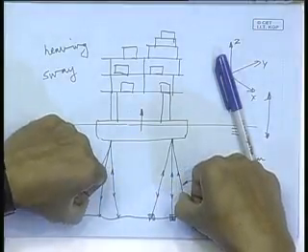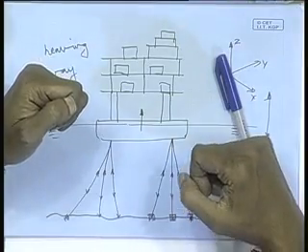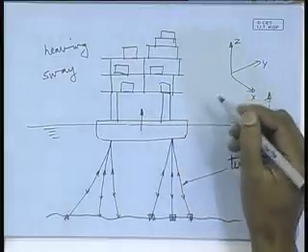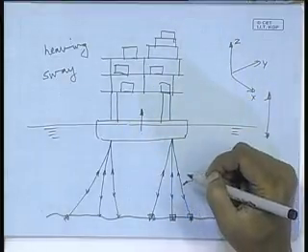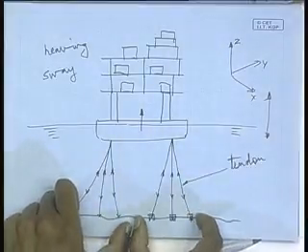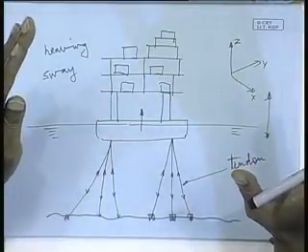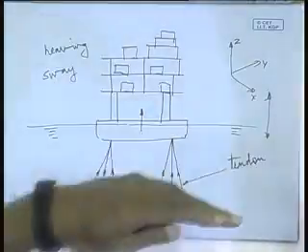So to minimize the heaving motion, these tendons or these ropes or these legs, flexible legs, are kept under tension, right? That is the concept. And so thereby your heaving motion is minimized, as well as the deployment of tendons is done in such a fashion that your swaying is also within a permissible limit, because you cannot allow it to sway kilometers, definitely not, right? Whatever is the permissible movement is possible, it's limited. So that is essentially the tension leg platforms.